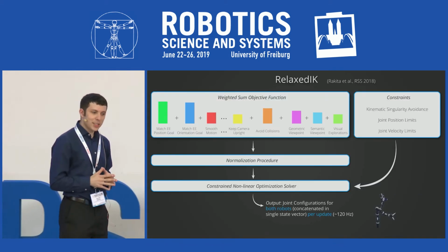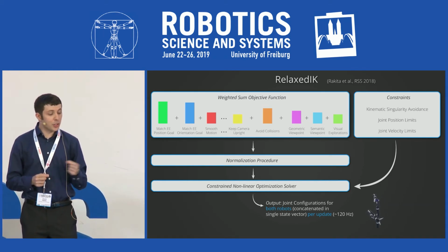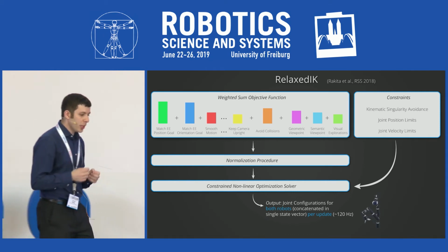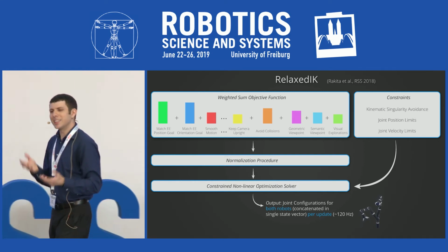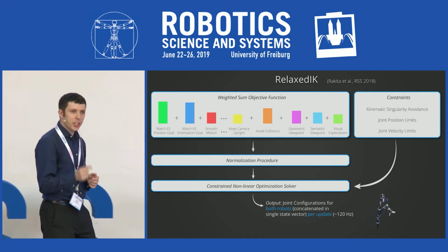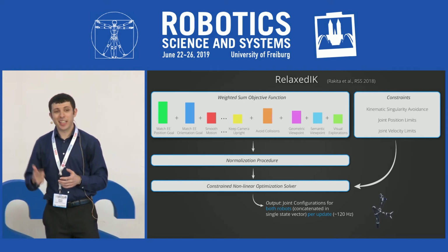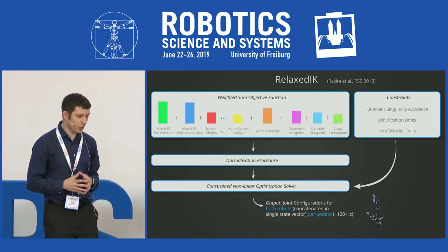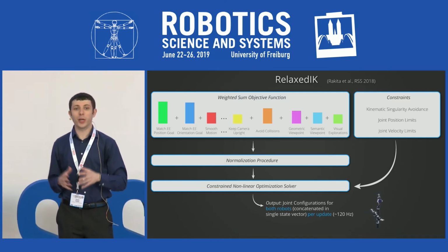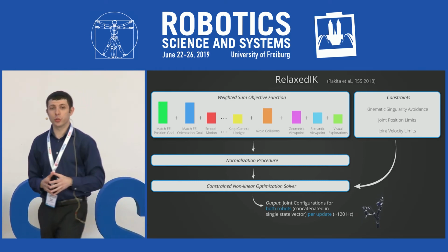We utilize the RelaxIK solver to achieve real-time motion optimization performance in our method. The solver uses a flexible nonlinear optimization formulation to account for motion synthesis problems that dynamically trade off between multiple objectives on the fly, and is able to achieve per update motions that accurately match end effector pose goals without exhibiting collisions, kinematic singularities, and joint space discontinuities. We incorporate our geometric, semantic, and visual exploration viewpoint adaptation types into the RelaxIK optimization formulation by adding additional terms in our objective function.